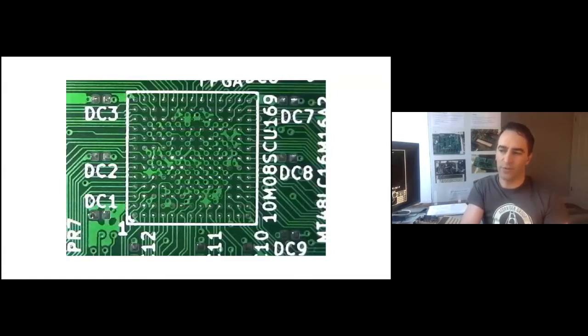Also, it lets you use smaller pads, which is great when you're running up against your design rule limits. I think if I did SMD for this, I wouldn't have been able to fit the vias in between the pads on the FPGA. Obviously, that's essential. There's no way I would get those signals out without that. I think people typically use more than 4 layers for this size BGA, but I was okay with some trade-offs, so this worked out well.